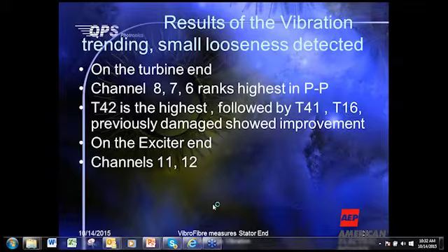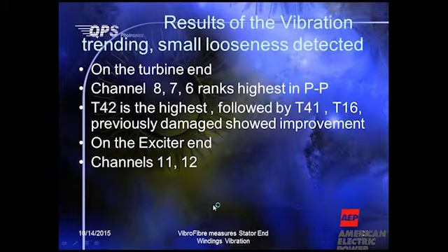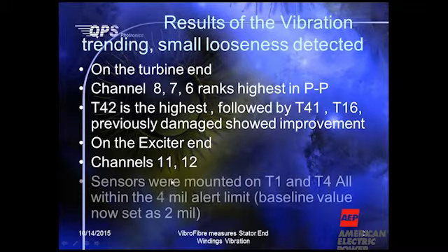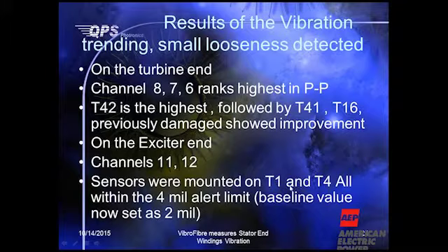Then on the exciter end, channels 11 and 12, which are showing T1 and T4, there is some magnitude of vibration, but they are within the 4 mil alert limit.